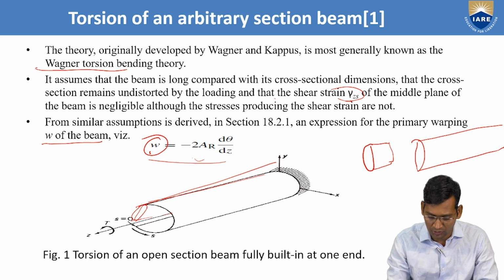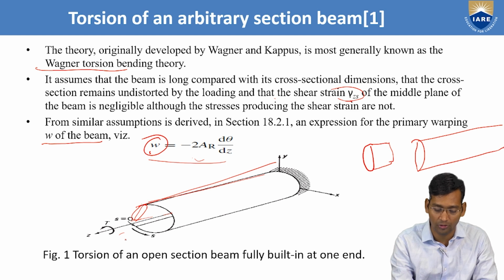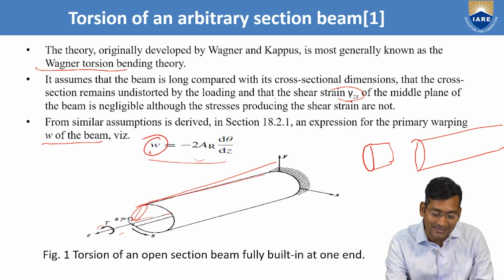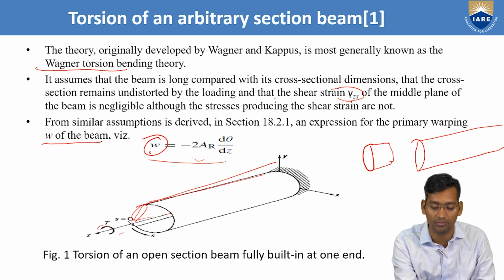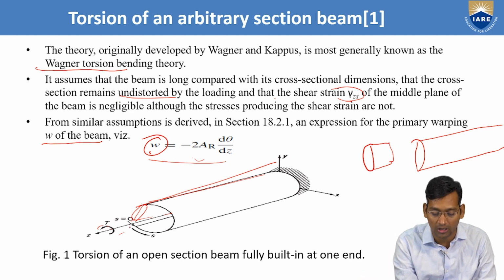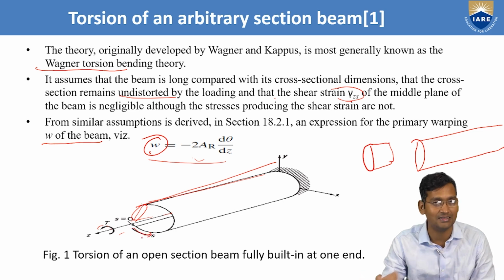So this is our figure on which we have to work. Just see along the Z axis, the torsion T is acting. At this shear load, for the open section, there is no distortion already. We had seen that somewhere here it is undistorted. So at that point S is 0, but all along the surface S is acting.